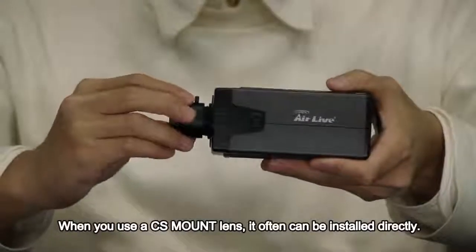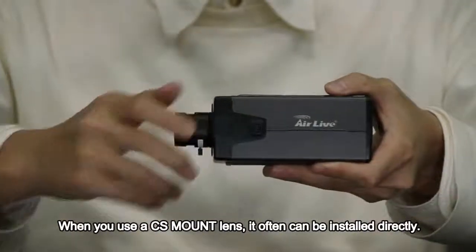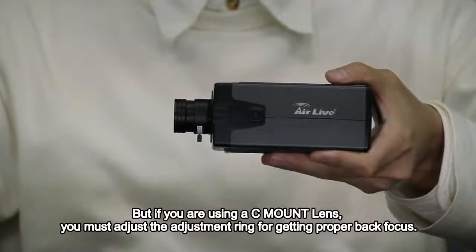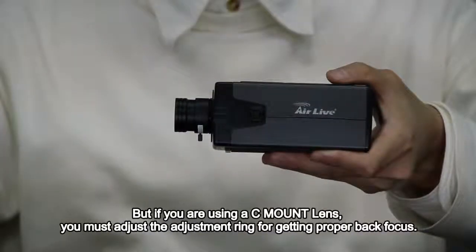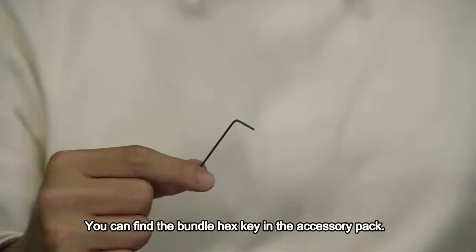When you use a CS mount lens, it often can be installed directly, but if you are using a C mount lens, you must adjust the adjustment ring for getting proper back focus. You can find the hex key in the accessory pack.